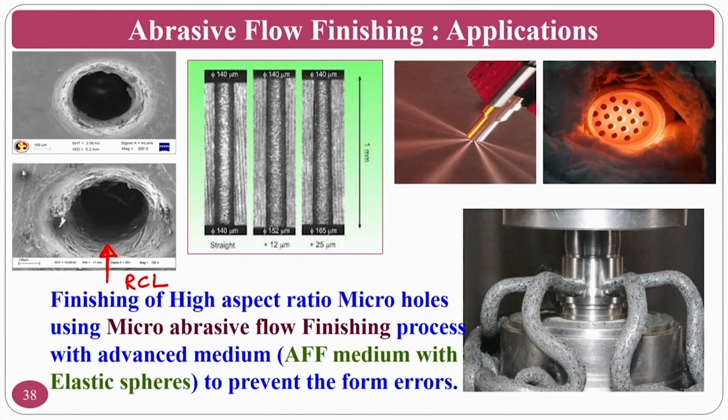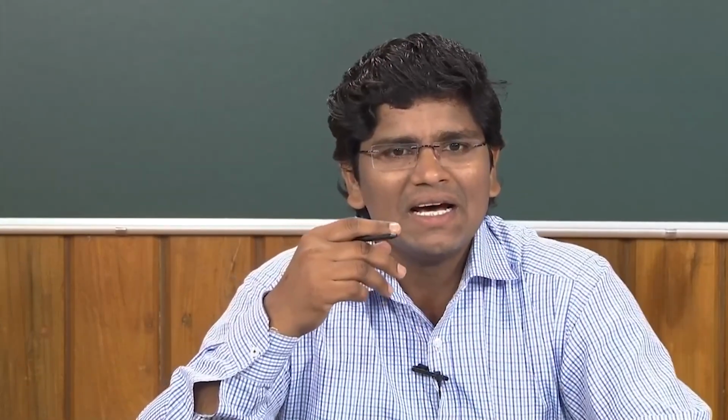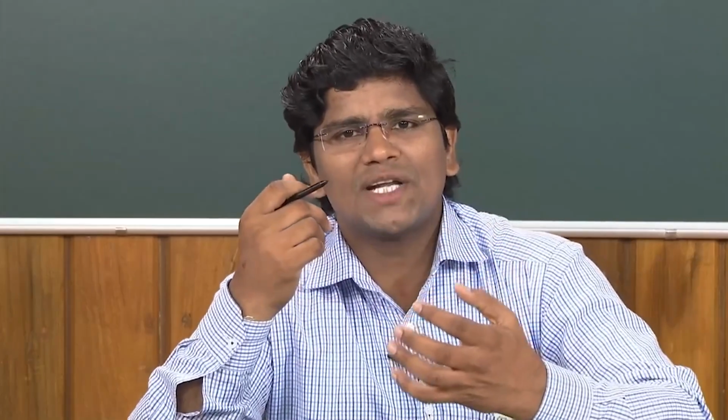If the material is unable to be removed, even with the atmospheric gases or laser assisted machining processes like air assistance, the material is not removed and will stay like a recast layer. Molten material will stay there in the form of a layer that is called the recast layer.